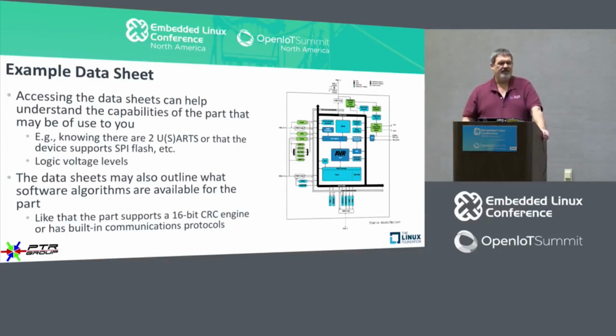So you definitely need to do a little bit of homework there, because if you try to plug a 5 volt RS-232 port into a 3.3 volt logic level port, it'll toast it. So definitely a bad thing. Data sheets may also outline a lot of information about the algorithms that the part supports.